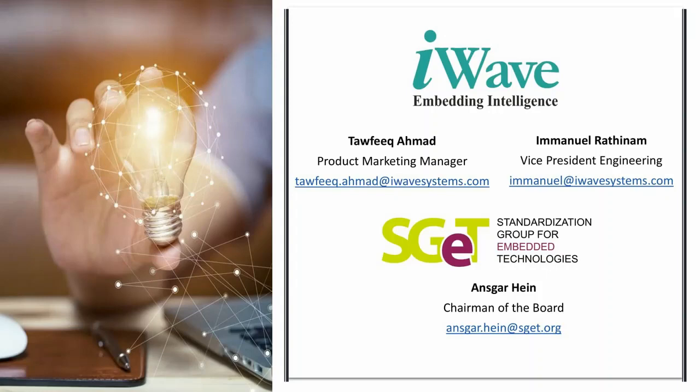And another one from Kenji. So I see 4 different sizes. Exactly, it is correct. All the pins are overlapping each other, so all are pin compatible. When you do a size 0, it is all the way pin compatible to size L. When you do a small size, it's backward compatible and forward compatible to all the 4 sizes. Similarly, the voltage pins and the ground pins are defined in such a way that it is completely pin compatible across all the 4.